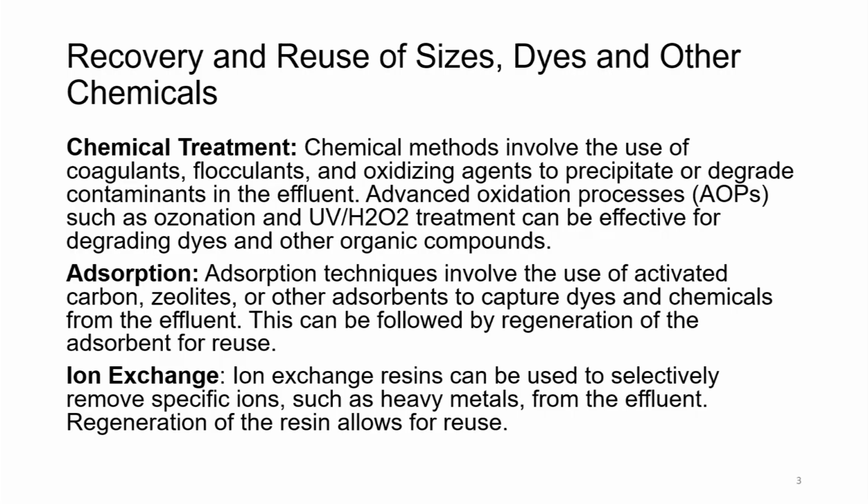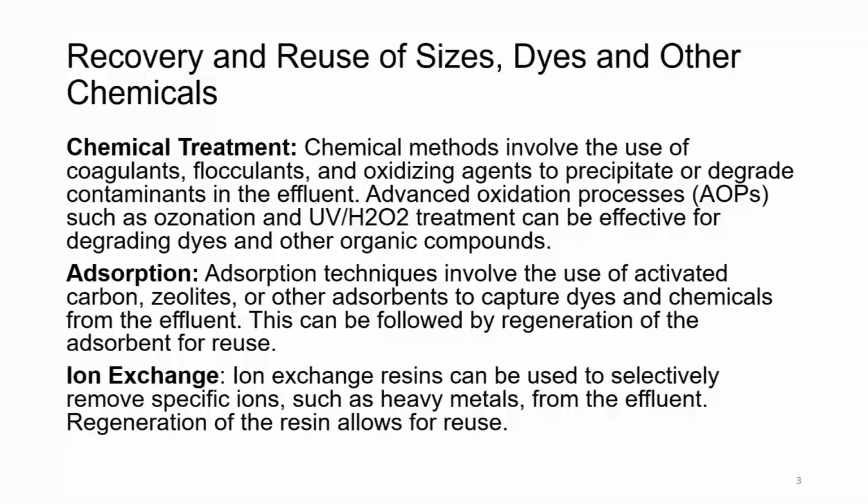So, when it is regenerated, there is an automatic recovery of that particular chemical, be it dye or heavy metal. Ion exchange. Ion exchange resins can be used to selectively remove specific ions such as heavy metals from the effluent. Regeneration of the resin allows for reuse.